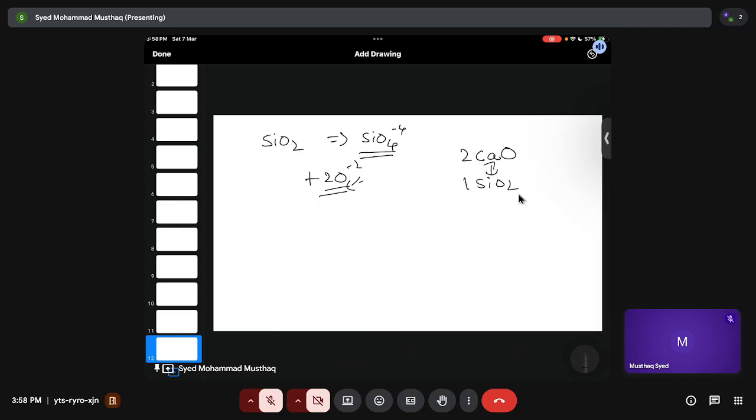So if my slag contains, let's say this is my total slag, then what is my silica concentration? If my silica concentration in my slag is 33.3%, with the remainder being calcium oxide, then my slag is called a neutral slag. Right? And why is that? Because whenever you see,